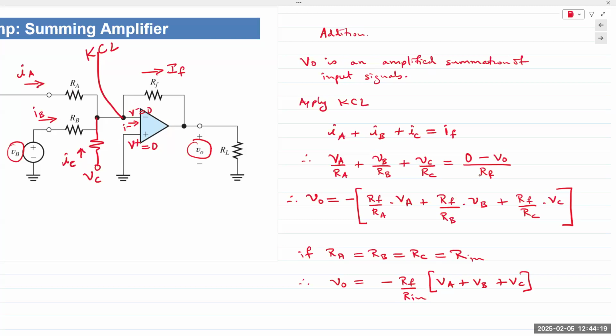If we wish each signal to be amplified by different amounts, we just keep the values different. Then each individual signal would have a different gain. The result is that all the voltages at the input terminals are summed up. And so the output would be VA plus VB plus VC plus VD plus VE plus VF, depending on how many inputs we want to give. It's as straightforward as simply connecting all of them together at one endpoint to the inverting terminal.